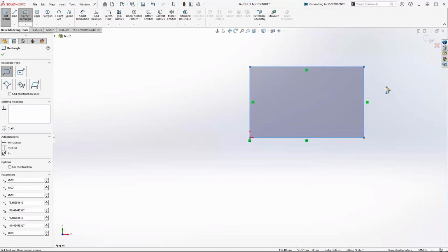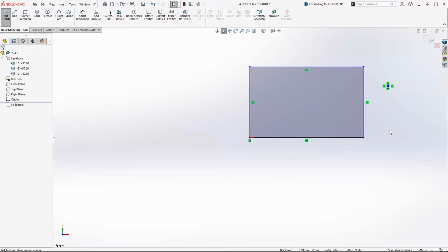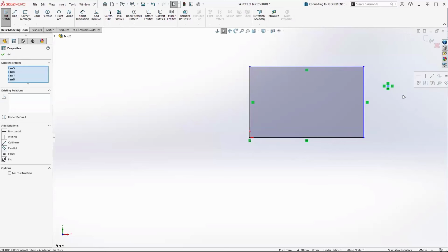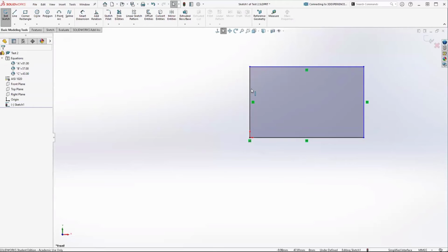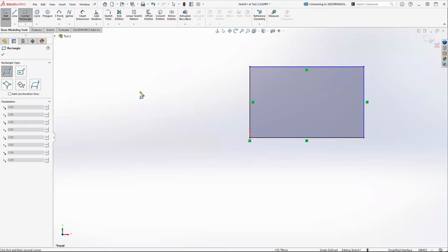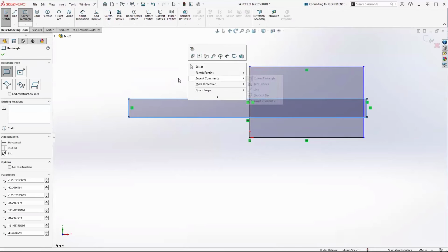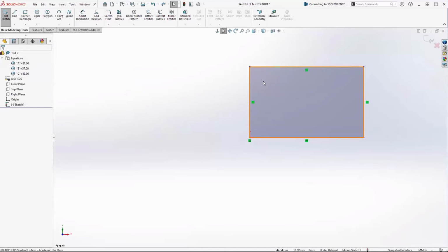If for some reason it puts a tiny little rectangle somewhere, you're going to try to fully define your part and you're going to have issues, and you're going to find out later that a tiny little line was somewhere. For almost every command in SOLIDWORKS, you can click, let go, and click again. Or something I found out recently, you can actually click and hold and press right click to stop it, which I didn't know. So another option as well.